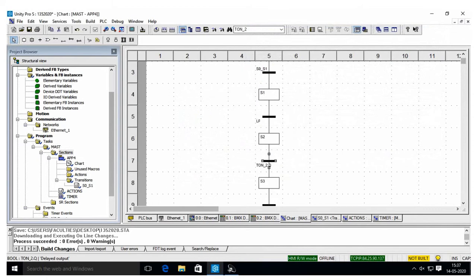Okay, after this, so once again I repeat, it is the initial position S0 to S1, it will reach by pressing all the 3 buttons. S1, drill motor will be on, and the cylinder will start to extend. To which position will it extend? Up to low position. S2, I'm performing the drilling operation for 2 seconds.